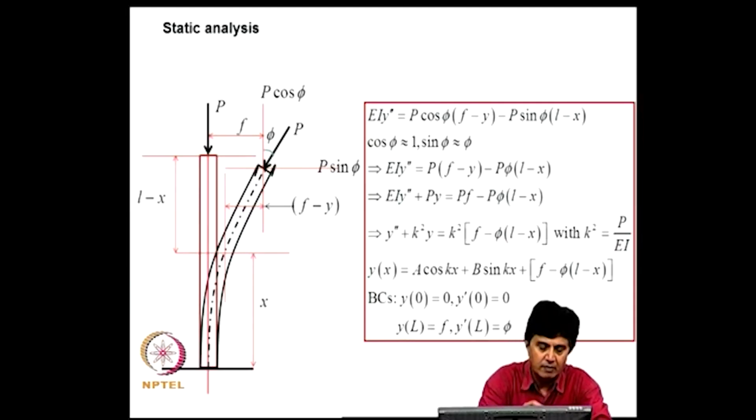See, when we performed the stability analysis of a beam where the direction of the load was unaltered, what was the conceptual framework within which we did that? We started with small values of P and incremented P in steps. At every step of incrementing P, we gave a slight perturbation to the system and the system gets into oscillations, and the presence of damping ensures that the system either returns to its original state or assumes a neighboring equilibrium position.